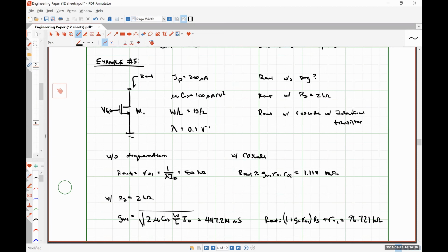We do have a constraint in as much as our second transistor needs to be operating in the saturation region for this to occur. We can't get by with soft saturation and crap like that with a MOSFET. It's either saturated or it isn't. So this is cascoded MOSFETs.